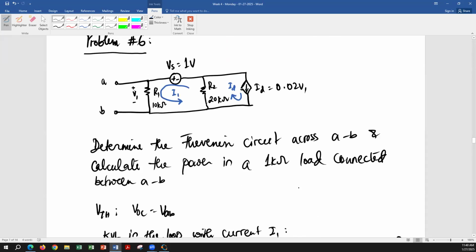In order to get R Thevenin, what should we do? Now analyze both methods. Anytime you're trying to find R Thevenin, analyze both methods in your brain: either you short circuit A, B, is that going to be easy? Or if you apply a test source and eliminate the independent sources, is that going to be easy? If we short circuit A, B, what's going to happen to the circuit?